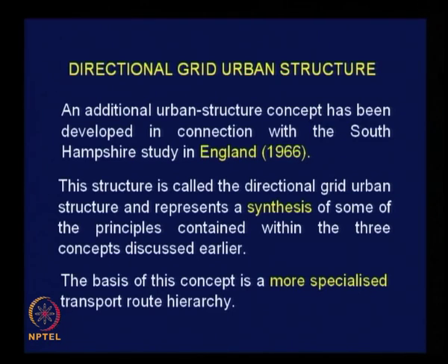We have basically had 4 categories of roads in all the previous cases, all the 3 cases: type 1, type 2, type 3 and type 4 roads. And each of these roads had a specific objective. Type 1 means emphasis only on speed and no emphasis on land access. Type 4 means full emphasis only on integration of road with land and no emphasis on speed.